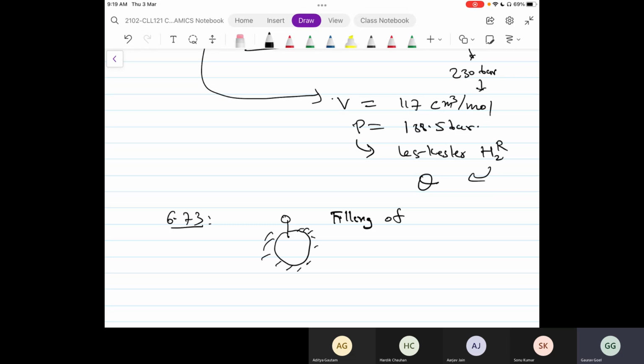So there we said we are filling an ideal gas. More realistic would be liquid nitrogen cylinders. So there also we're dealing with nitrogen, but in the ideal gas state. But typically you don't store nitrogen under ideal gas conditions, you store it under liquid conditions. Okay. So again, the process is the same: from a compressed air line, or compressed N2 line in this case, you are filling this cylinder. Initially, there is no gas in the cylinder, there is a vacuum.